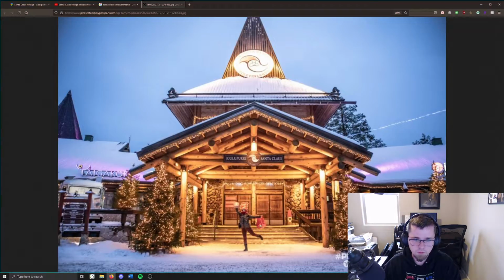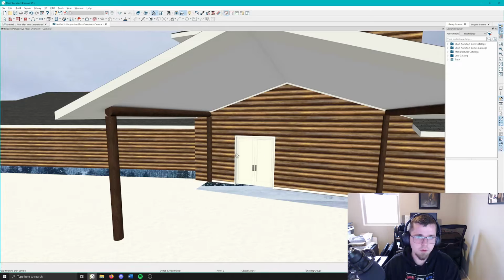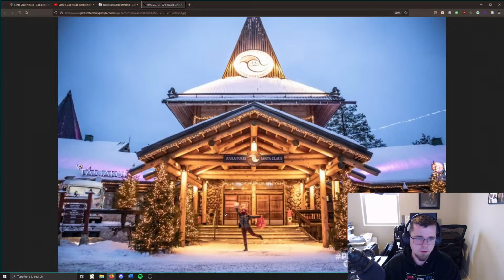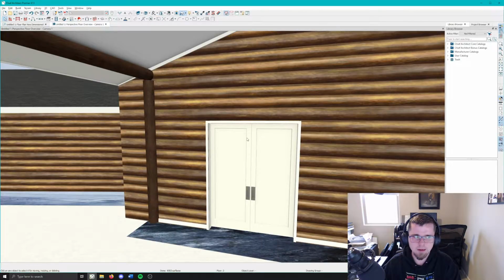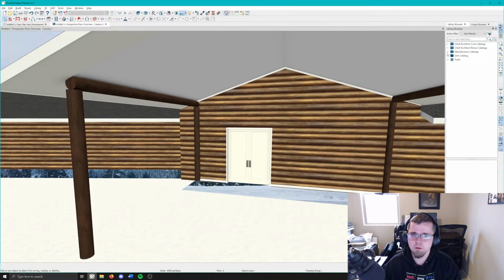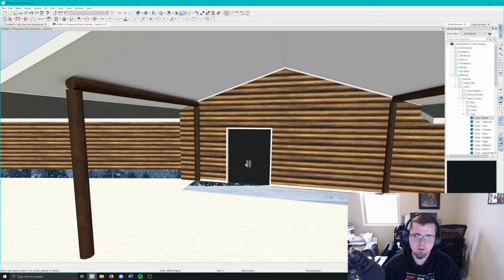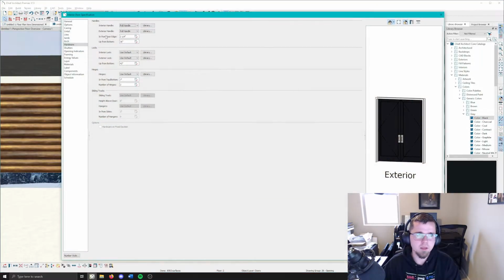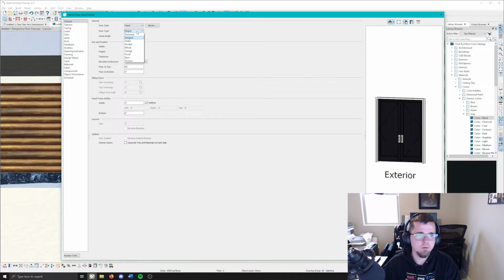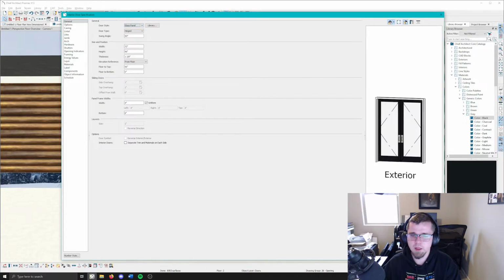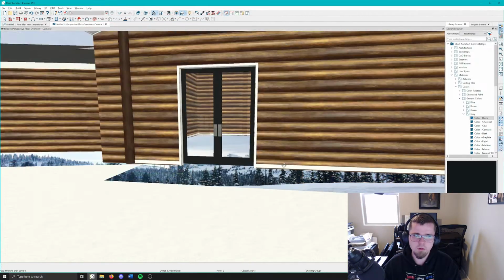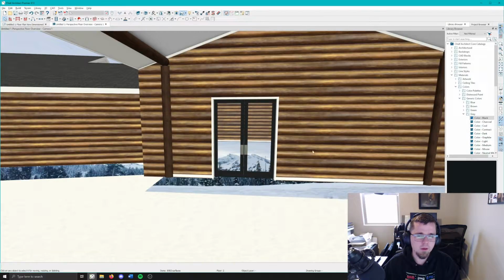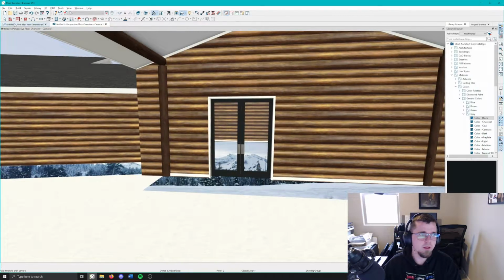I can go in and change up the, looks like there's a casing here, a little 2-inch or so casing, so that's fine. Looks like it's actually black right there. So I can go in here, let's go to our materials, colors, generic colors, grays, go black. I can just paint those black. Oh. Wonder if I didn't actually change this to a, yep, panel. I messed up. Glass panel, there we go. So yeah, it's closer. So obviously that wood color, I'm gonna ignore that for right now.